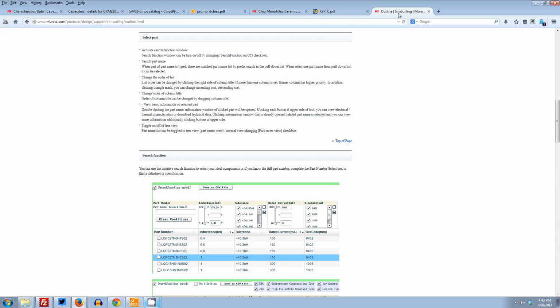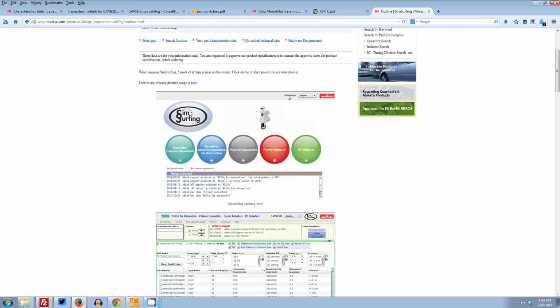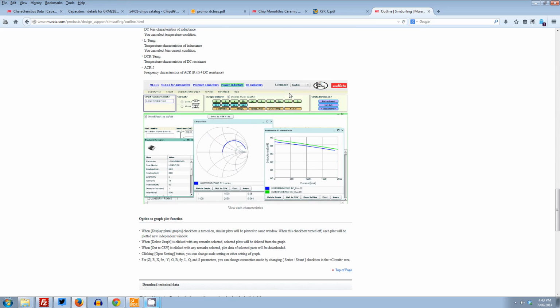Now, a couple of the manufacturers, namely Murata and AVX, two of the better manufacturers in this field, are always analyzing and trying to correct this. They're always improving their manufacturing processes to try and eliminate this kind of effect, although it's next to impossible with the class 2 capacitors. But at least they're aware of it, and they do give you tools to actually simulate it.